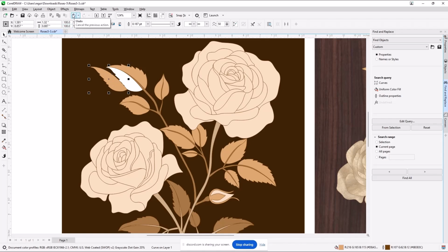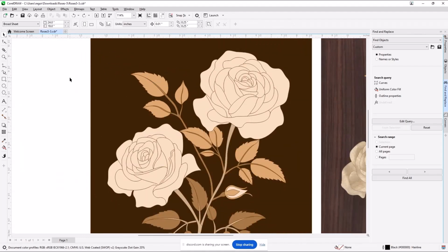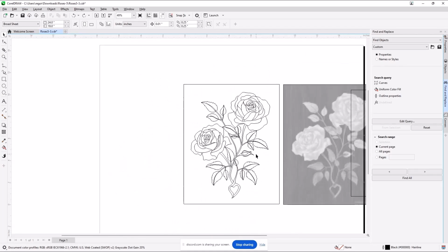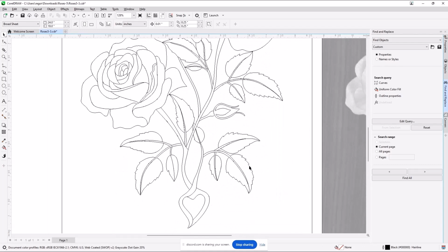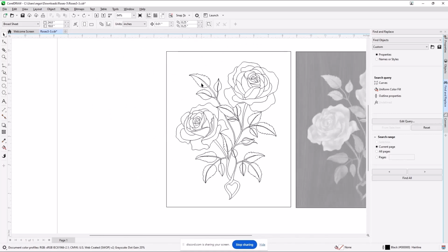Remember, this one's the one I use all the time. I moved it over there. I don't know why. I wanted to look at it. Now, if I want to move it back and I don't get to do an undo, it gets really slow, because you have to zoom in, find the nodes, align them up, and touch the pieces. I routinely bump stuff, and about a half hour later go, oh, that's in the wrong spot. So a word of caution: spend a few minutes with anything you load, looking at it in wireframe and deciding whether or not it's ready or safe for attempting the image paint.